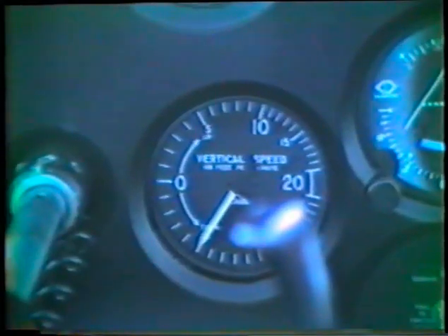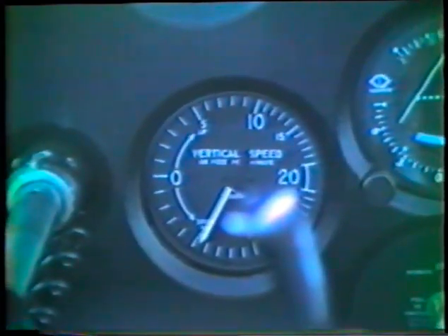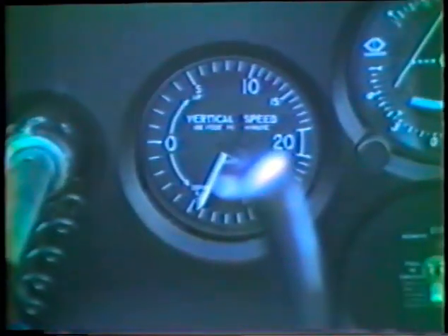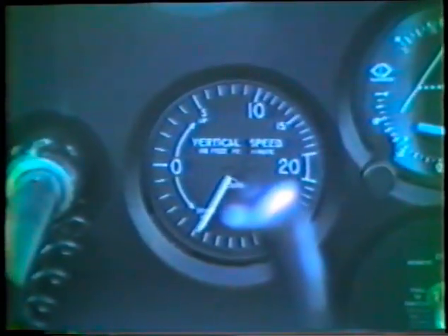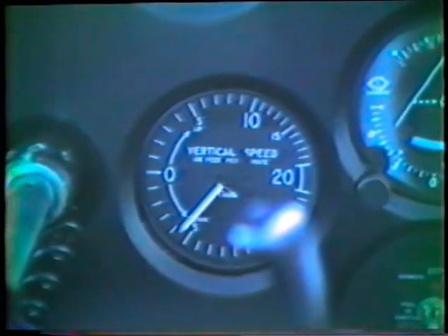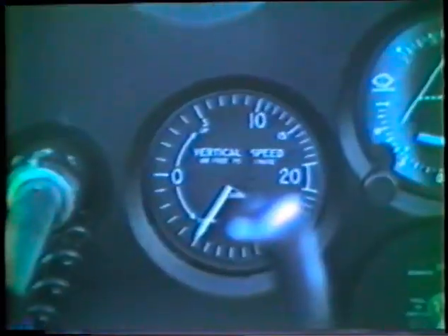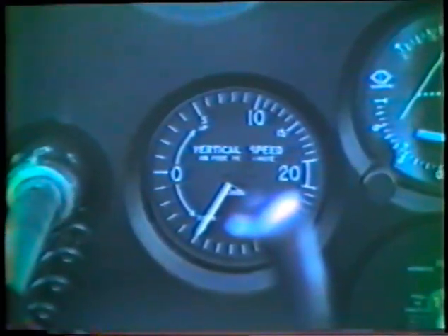There is a particular descent rate which will keep the aircraft on the glide slope with the existing wind and power conditions. This is the reference descent rate. It must be determined by bracketing on the VSI in a manner similar to bracketing the reference heading on the DG. Pitch changes are made with reference to the artificial horizon and evaluated on the VSI.